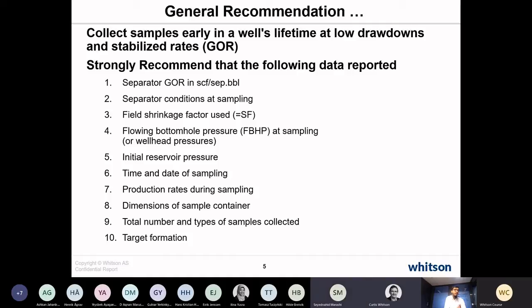It depends on the process that you're wanting to model with the equation of state, the range of pressure and temperature, and composition. So if you're only doing reservoir simulation, it'll only be at reservoir temperature. Of course, you'll have the surface processing to get products. You'll need the separator and stock tank pressure and temperature. So you'll need temperatures from stock tank to reservoir.